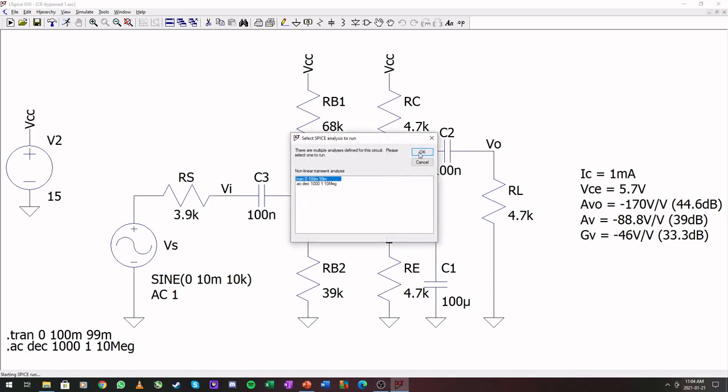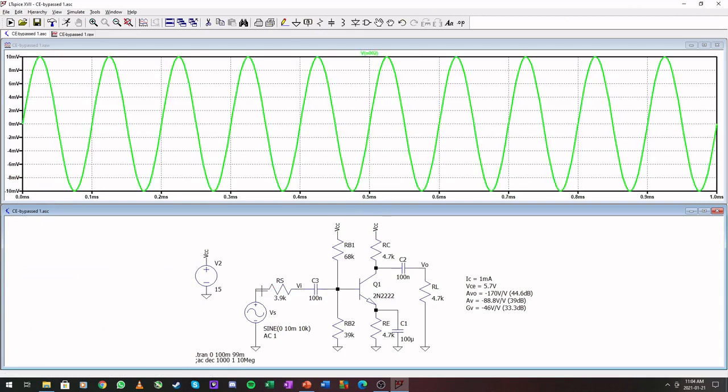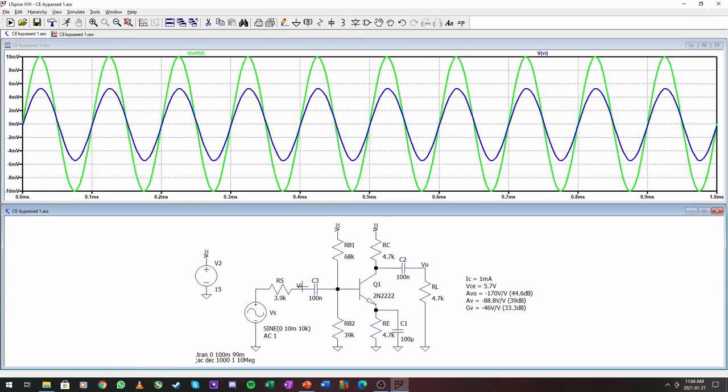So if we run our amplifier, let's first do a time domain, 10 millivolts in, then we have a division, and we remember that our input impedance and our source is roughly the same. So this 10 millivolts goes down to 5 millivolts going into the amplifier.